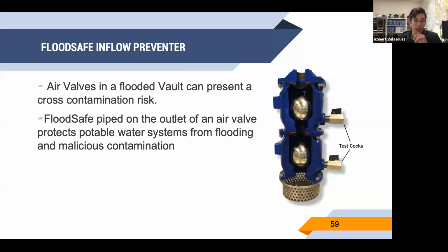And so these are available to you to be able to protect against cross-contamination, and you can test them as any backflow prevention device. They should be tested annually. So on this test box, you can put a clean water supply in there and raise up the balls and make sure that you don't get water coming out of the test cock.